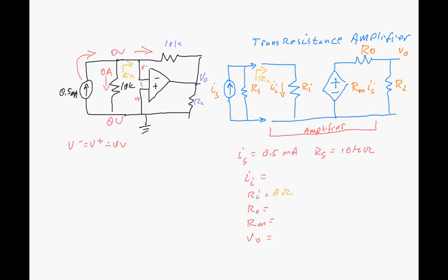It's an ideal situation for this op amp, and for this signal generator. And actually, we already know that since this is a voltage source on the output of the op amp, its output resistance is 0 ohms.